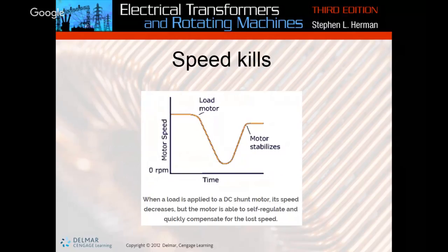So a little bit of where I would see this is maybe on a conveyor belt. Like over there in Wyoming, I worked on a lot of coal conveyor belts, and part of what I did was work on these DC shunt motors. When they would start the coal system, they knew that, hey, listen, we can't have this belt loaded and try to start this motor because it's not going to have enough torque to. So part of their procedure when they got done loading coal at the end of the day was they made sure that the entire belt was clear. And then that way, when they started the belt back up in the morning, they could get the belt up to speed, whatever speed they wanted to, and then start loading it down, and that would maintain that speed.